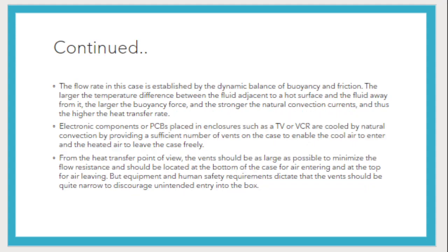The flow rate in this case is established by the dynamic balance of buoyancy and friction. The larger the temperature difference between the fluid adjacent to a hot surface and the fluid away from it, the larger the buoyancy force and the stronger the natural convection currents, and thus the higher the heat transfer rate.